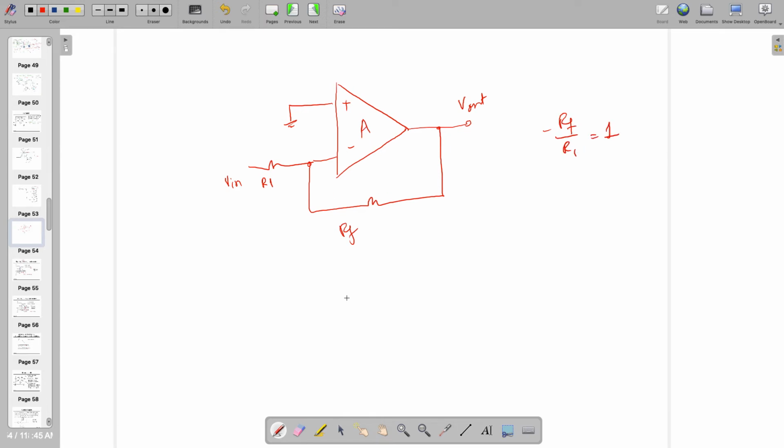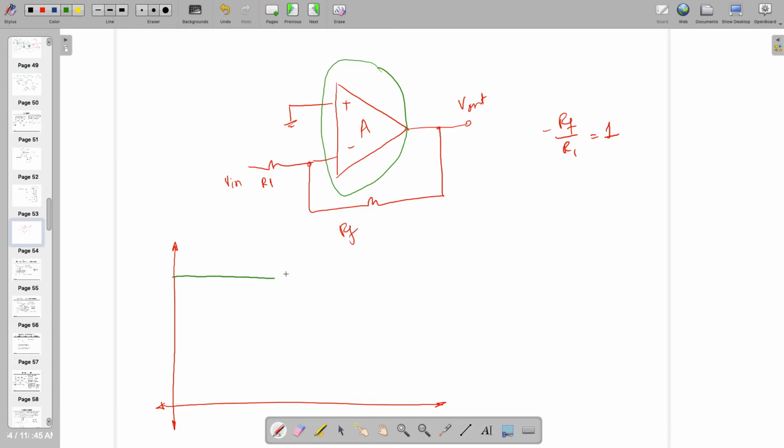If we are drawing two different plots, one plot is about open loop gain, meaning open loop only the internal one by removing the rest of the things. If you are drawing that open loop, it will be like this. If it is having a two-stage op-amp inside, after compensation and all, you will have three poles.